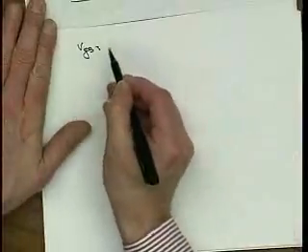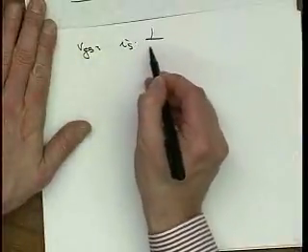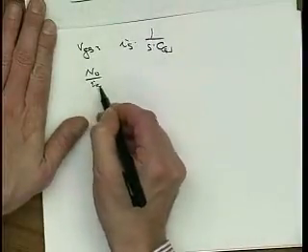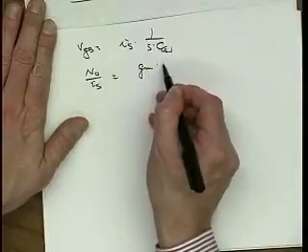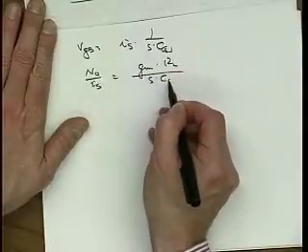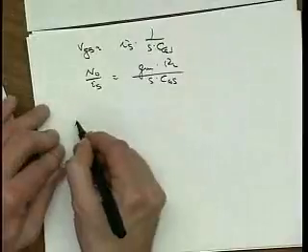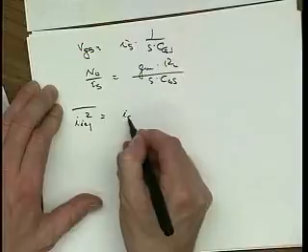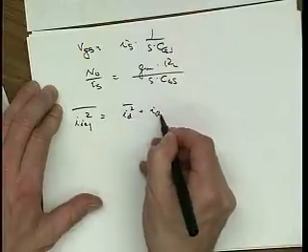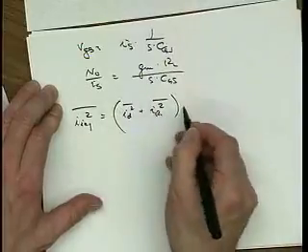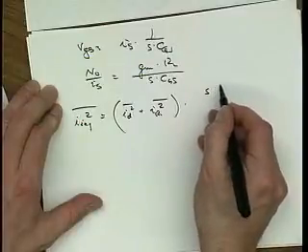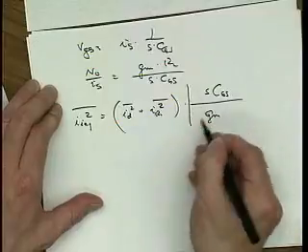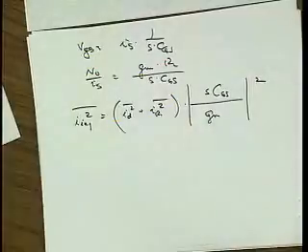VGS is now equal to IS times 1 over S times CGS. And V out over IS is equal to GM times that, GM times RL over S times CGS. And from that I can calculate IEQ square is equal to ID square plus IRL squared times S CGS over GM, squared.